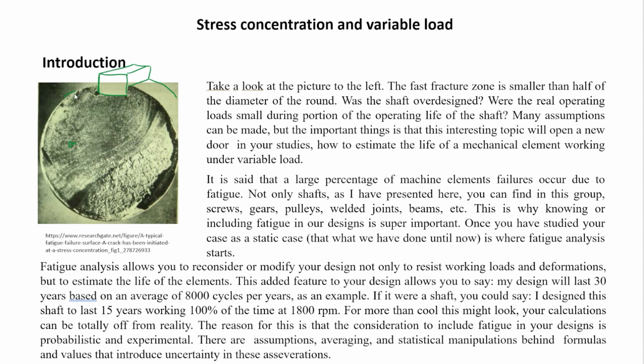Now, in this specific case, for this figure, it is said that the failure started here. Let me put it with another color. And the reason for that is that if you notice, the surface of the shaft in the exterior part is very consistent and smooth, but in this keyway, you're going to find that there are some sharp corners here, these ones here.